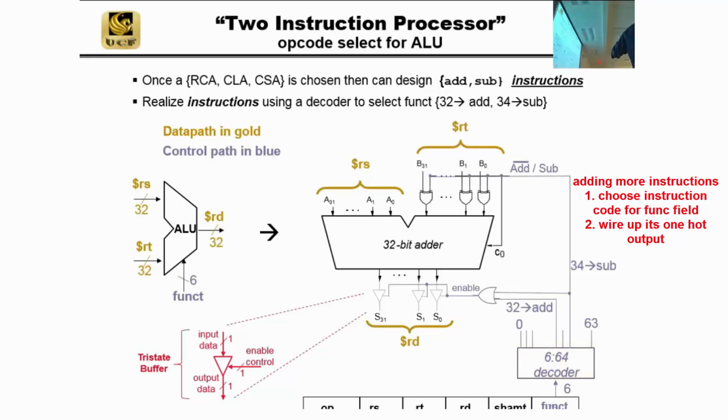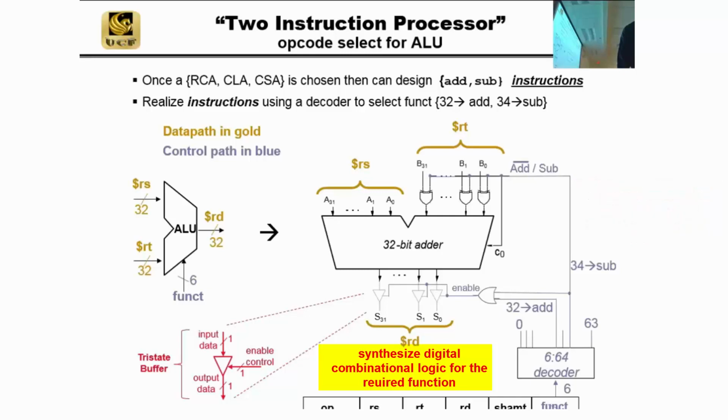Of course, you can use K-maps, and we use design tools like Verilog, and then it will synthesize the actual gates. But a lot of times we use these types of approaches, and these are good things to know. Like if you want to make a conditional NOT, you can use XOR. And that's what we have going on here, where we show you some of the basic approaches to design this. So I'll let you ask any question on control path. Can you see the connection between the bits of the instruction encoding and how it activates the circuit to compute?